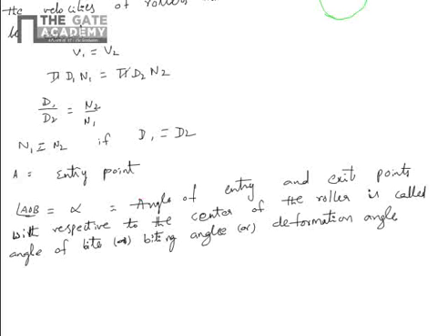So in problems they may ask with different names, that's why I am giving all names. It's better to know all the names. So delta H, H0 is the initial thickness, H1 is the final thickness. So delta H is equal to H0 minus H1, which is the change in the thickness. The assumption is the width of the strip remains constant, only length and height will change. Width of the strip remains constant. So the volume of the material before rolling is equal to the volume after rolling.